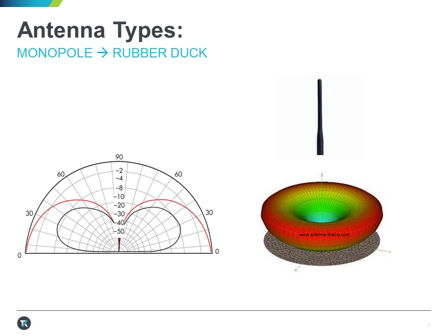These types of antennas are both very useful as we get closer and closer to the source of interference. It's very common for us to use these types of antennas as we get within what I would call visual range of the source of interference. These antennas combined with the use of an attenuator allow us to essentially zero in on the location of the actual transmitter itself. The technique basically is to start adding attenuation as you get closer and closer to the source